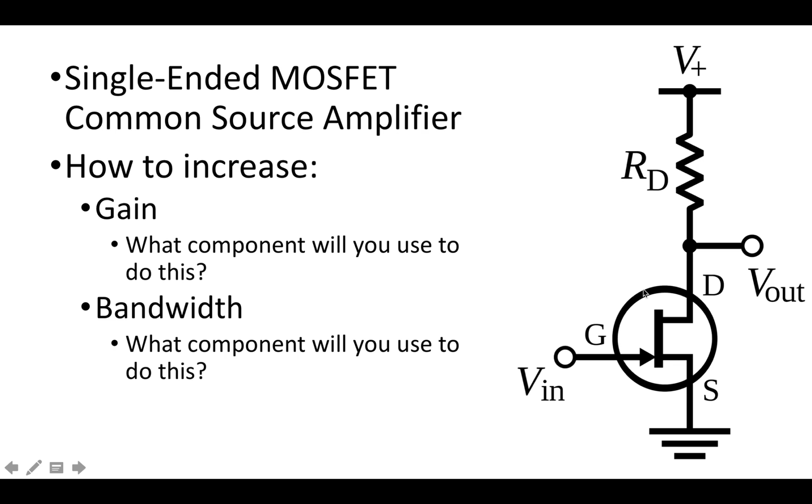It also increases the capacitance. When the capacitance increases, the bandwidth decreases, which promotes DC gain. And additionally, when W increases, ID increases, and this makes our output swing decrease as well.